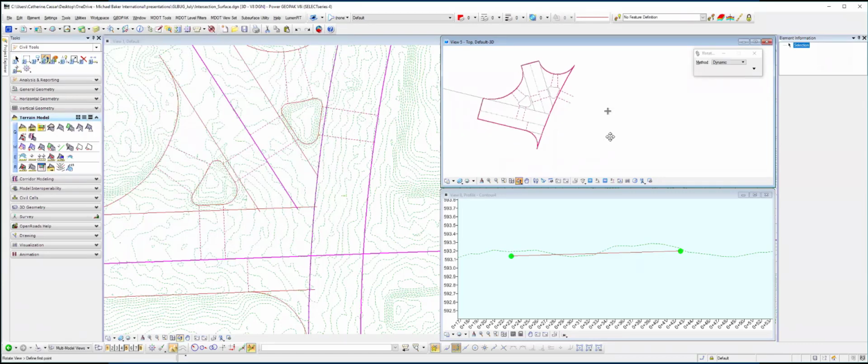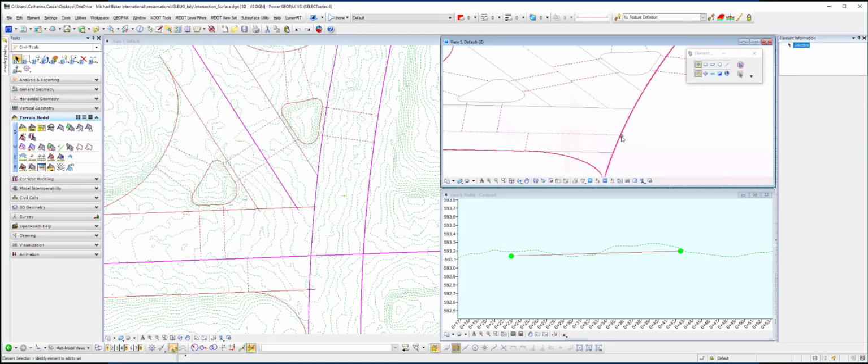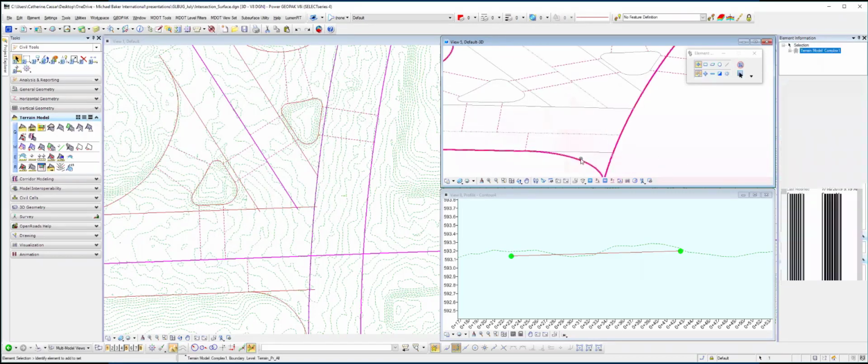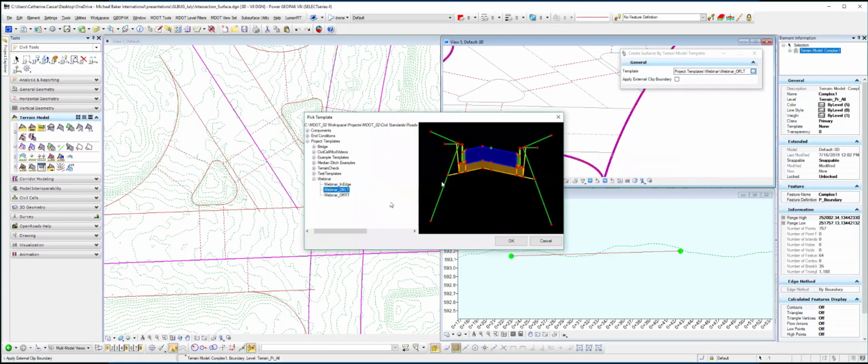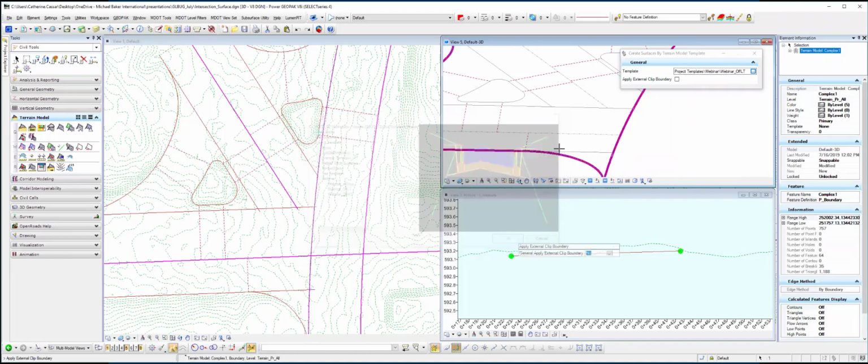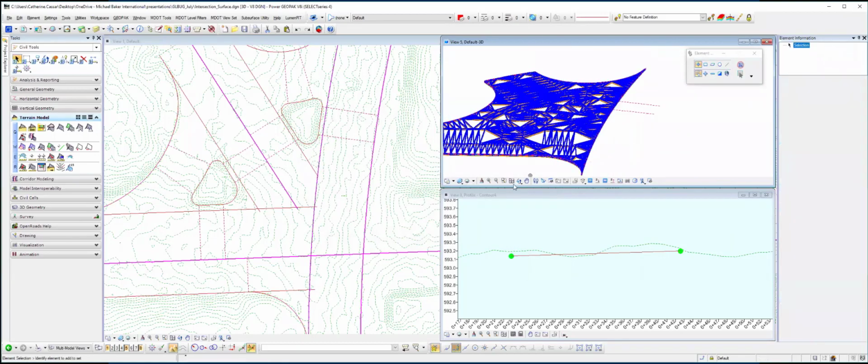So from there, you get the option to add, you want to go down and add your other layers. And that's just done using your standard surface template. Surface templates work, they just take whatever's from the green dot, whatever down. Obviously, if this was the road section, you want to apply the same section to your intersection. And you get a surface model.